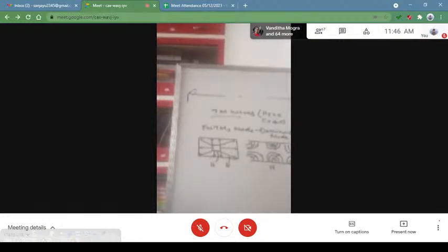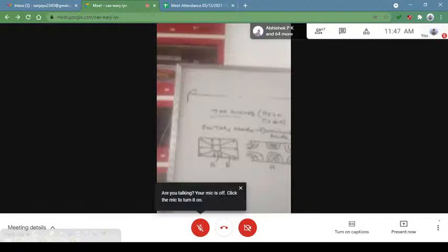So getting the field components for the TM wave is one and the same. The only difference is that, instead of using the wave equation del squared E equal to 0, here we use del squared H equal to 0. Instead of del cross H, we consider del cross E as the curl equation, but del cross H is also used. We must have at least 6 auxiliary equations to find the 5 components of the electric and magnetic fields, as mentioned earlier.